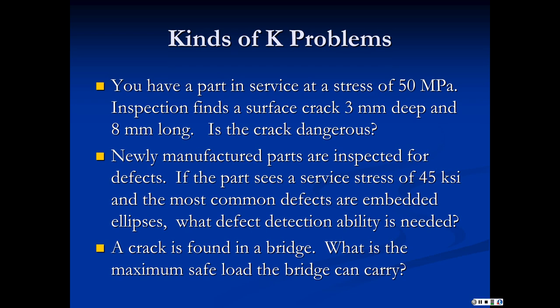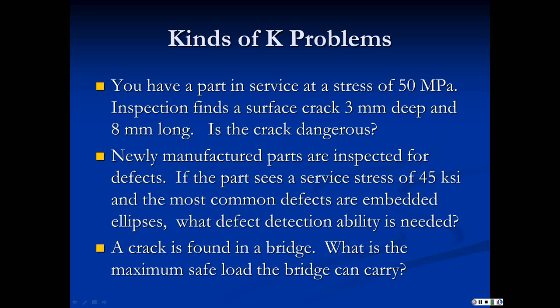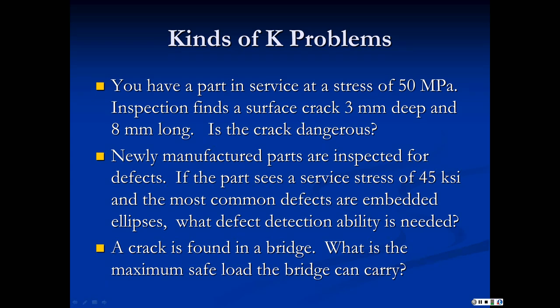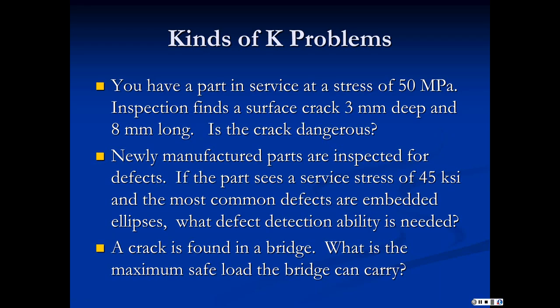Another kind of application would be you're making parts, maybe you're making pressure vessels or you're welding I-beams, and they're going to be inspected for defects. Now, you know the service stress you're designing for, and you know the shape or the kinds of defects you commonly make in your process. So maybe in welding, you know you're going to have an embedded penny-shaped flaw due to incomplete penetration of the weld or what have you. So now you know the basic geometry, you know the surface stress, you know the material because this is what you're manufacturing. And the question is, how big of a flaw would be dangerous if this is my service stress? And then that's the flaw that I have to be able to detect. That's how good my X-ray machine needs to be.